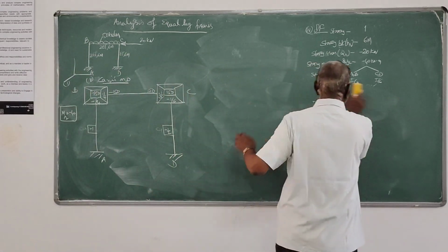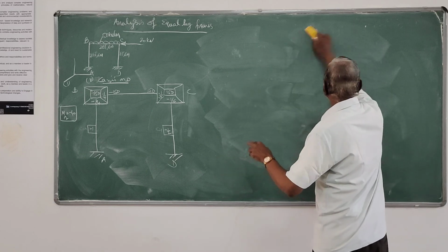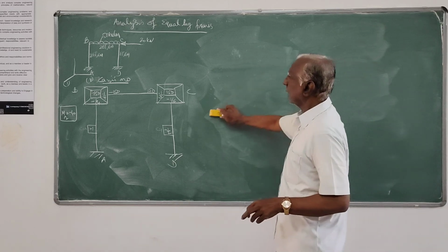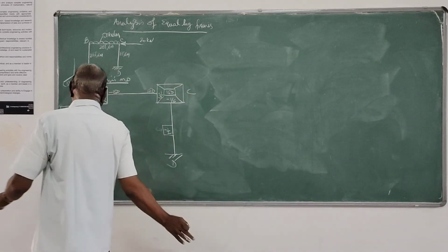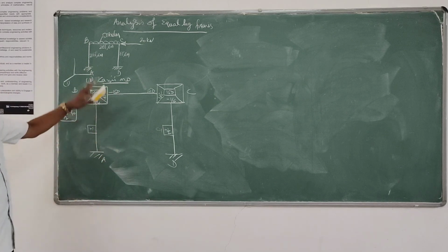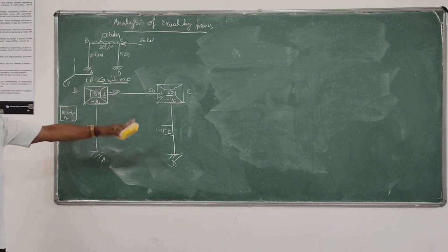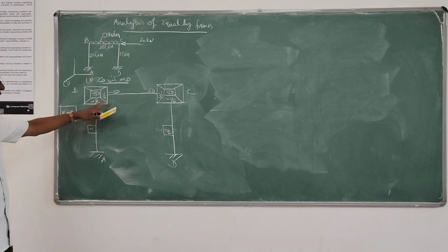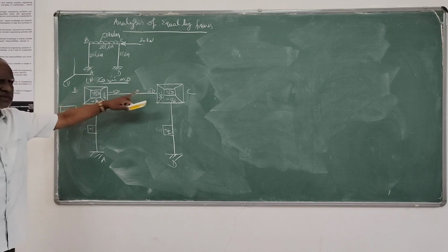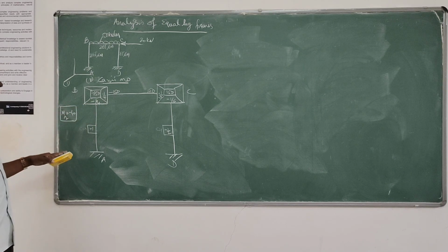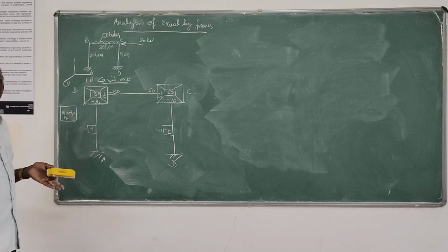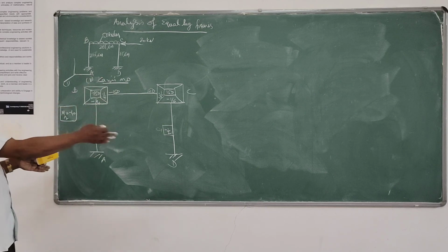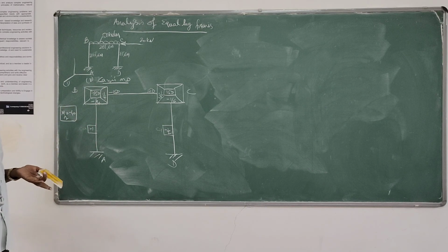So all the values which I have determined in earlier steps 1 to 4 I have transferred onto the diagram. Now I will concentrate only on Kani's moment distribution in this diagram, cycle by cycle, until convergence occurs, for the rotation contributions at each of those member ends as well as the story contributions. Then I will use that formula for finding the final moment.